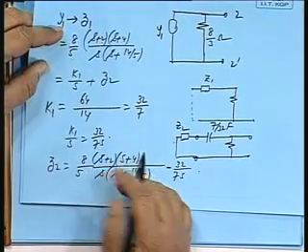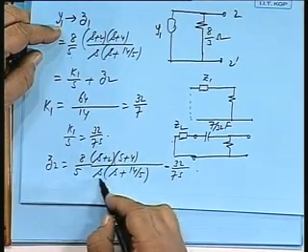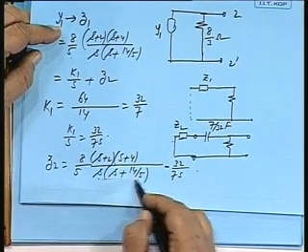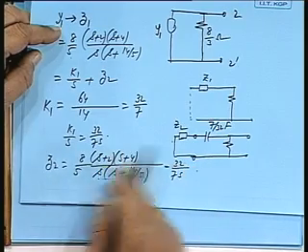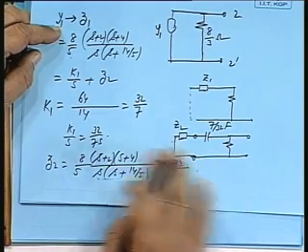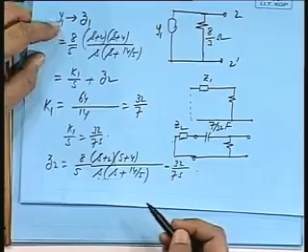The other alternative is, you can make partial fractions. Since there are only 2 poles, you can make partial fractions. Remove that, one of them will be 32 by 7s. So, remove that, whatever is remaining will be your Z2.